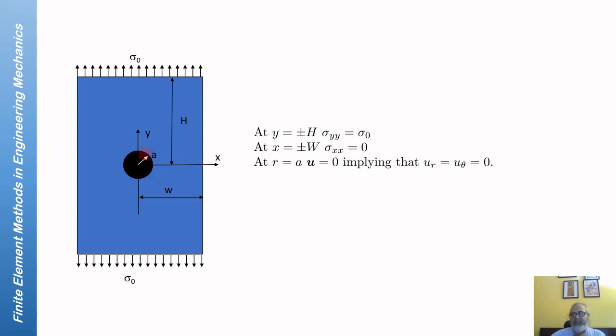So it is basically like specifying, you can remove the rigid particle and you can specify displacement boundary conditions here, and this would be part of your del Vu, and the rest of the boundary would be del Vt. All other boundary conditions would be similar to the boundary conditions on this face, and on this face would be similar to what we had in the previous problem.